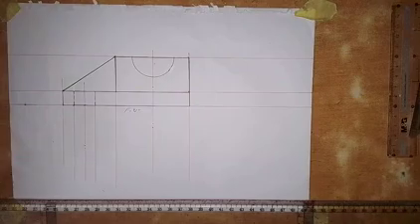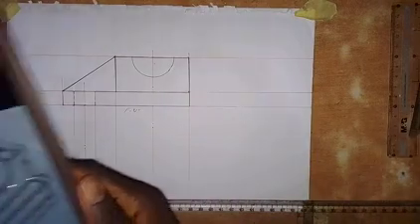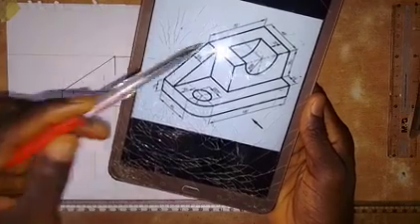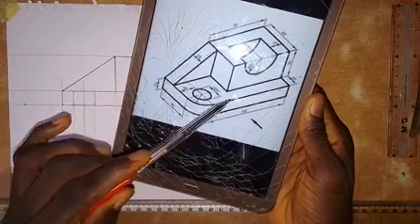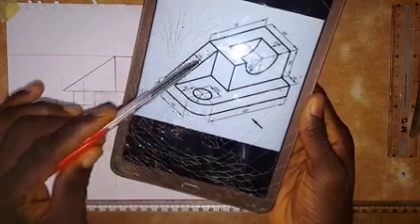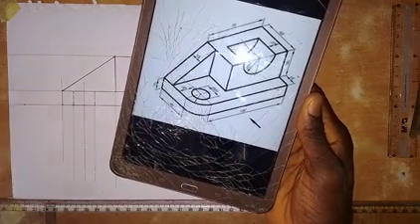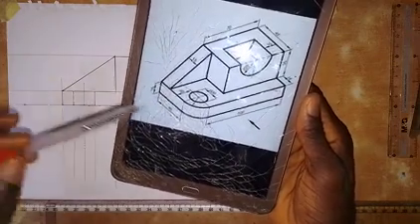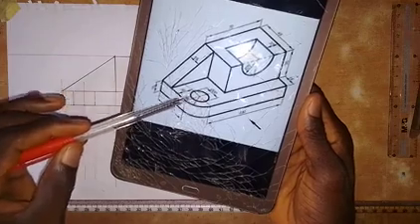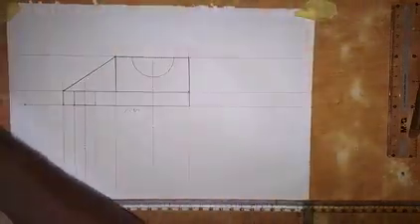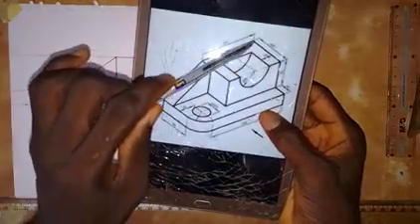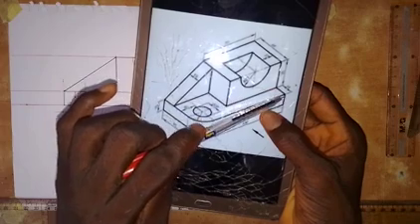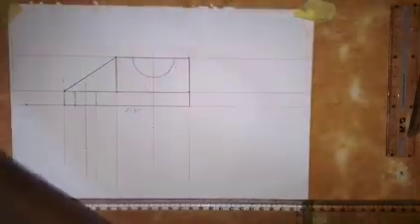Alright, so let's go and draw the top view. For the top view, what do we see? We see the surface like this. We see the surface, and then we see this rectangle. So those are the things we have to put together for the top view, including this circle that we have here. So let's look at the dimensions as we have here. From here to here is 45, and from here to here is 15. So in total that is 60 millimeters.